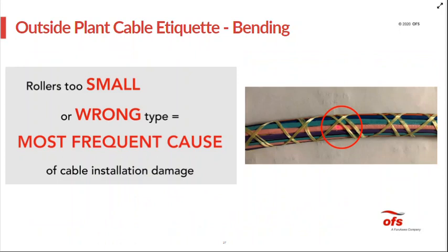If you look closely at the photographs, you can see that the rows and the aqua tubes are very flat. They've been crushed. You can also see this was an armored cable. You can also see little crosshatch marks on the buffer tubes. Those are actually indentations that were caused by the corrugations of the armor layer. So there was enough compressive force on this particular cable that the armor corrugations indented the buffer tubes. And then you can see the broken fiber. Broken fiber is indicated by the helium neon laser light that's leaking out of the broken fiber there.